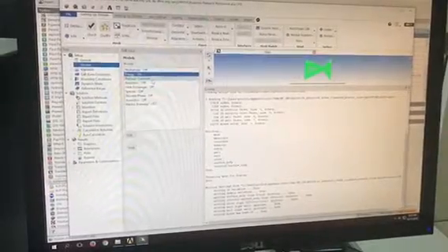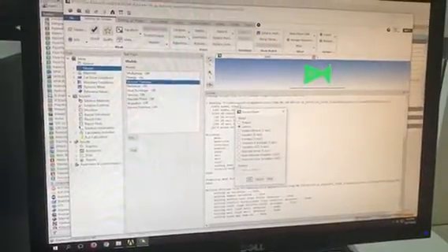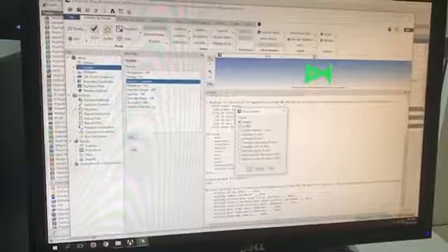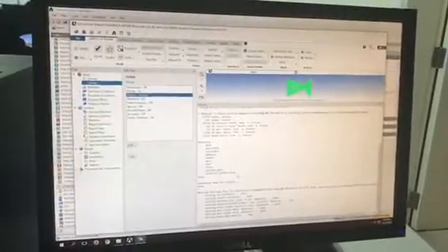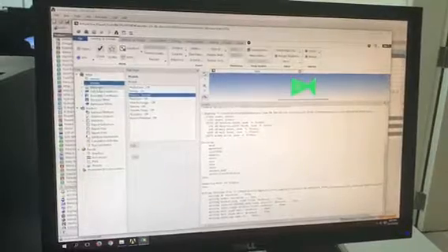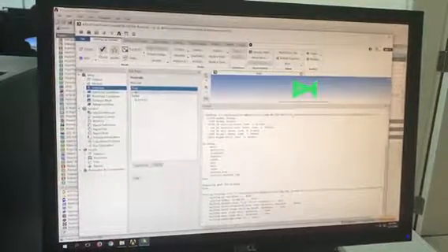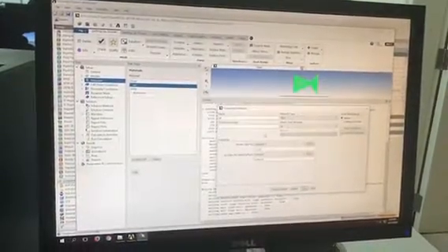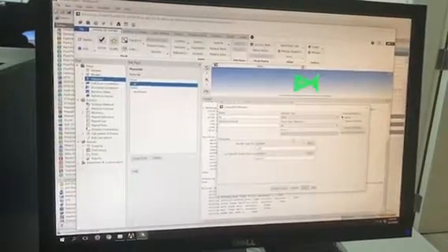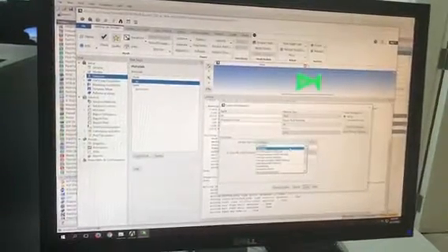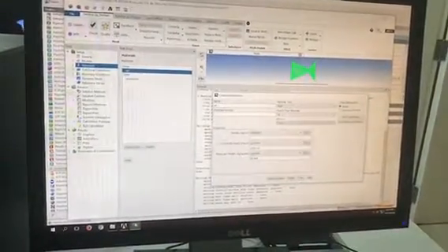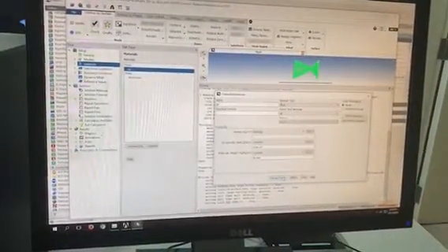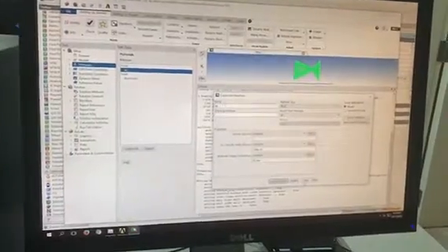And you go to the viscous, you want it to be inviscid. Okay, so afterwards we go to the materials. Click on the air. We want the air to be ideal gas for the sake of this project. We have to click on change and create because I forgot to do it the first time and I experienced errors.